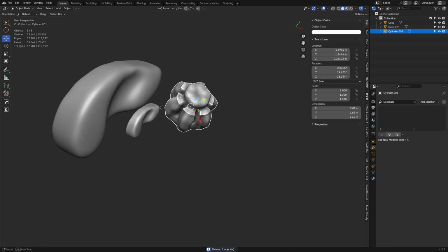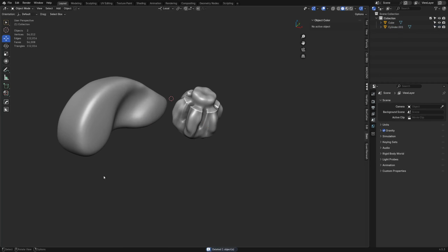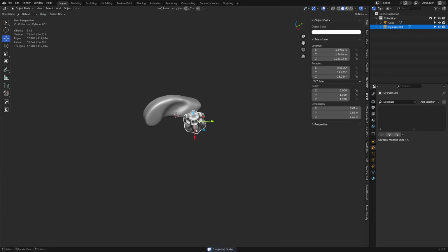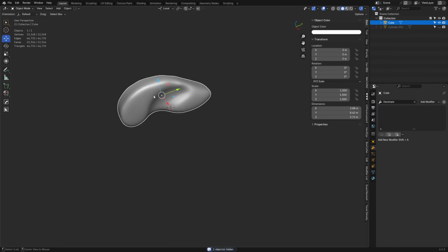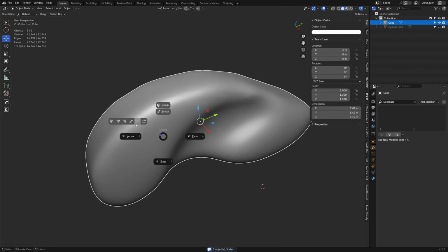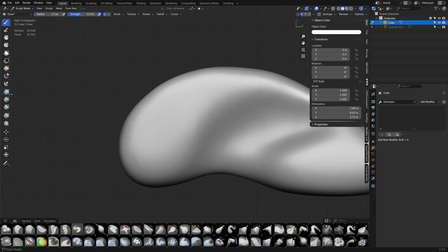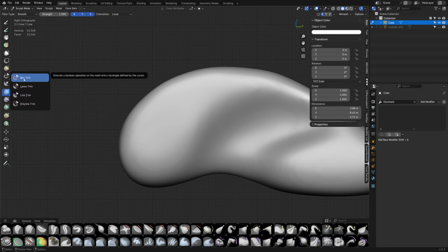So here's the thing. Let's do some big edits first. We could maybe save this thing for later, just hide it. I don't know if we're going to use it, but let's just do some big edits here first. I think we're still not quite done with those. We already kind of did mesh filter, but we have the trim tool, for example. We got box trim, polyline trim, lasso trim. It's the same with the mask tool. We got those same options.